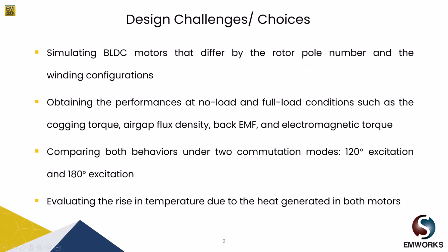So to begin with any BLDC motor, there are a few challenges, a few choices that the designer has to make. First, what should be the rotor pole number, and we need to simulate this BLDC motor with different rotor pole numbers and different winding configurations to evaluate its performance. Also, once we have the model ready, we need to obtain its performance at no load and full load conditions